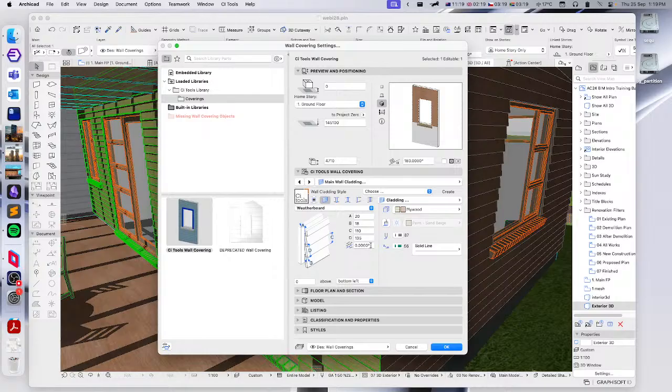So if we set this to say 90 degrees, the weatherboards will be running straight up and down across the wall instead of side to side, as it were, horizontally or vertically. Or you could put a different angle on there if you want to. I hope you don't, but if you do need to, the option is there. But generally, you'll probably just be switching between 0 degrees and 90 degrees to get them horizontal or vertical.